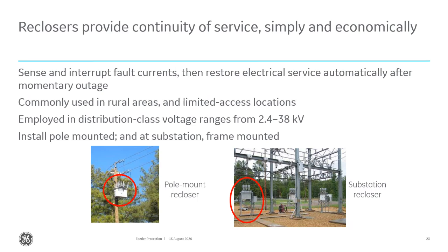Commonly, auto reclosers are pole mounted, but there are cases where they can be pad mounted for underground applications. They are usually deployed at distribution class voltage levels. At transmission level, we don't use auto reclosers. We use the breakers as auto reclosers because the short circuit current is much higher, because of all the sources in the transmission system. Reclosers are not going to cut it to interrupt those short circuit currents and for the continuous rating. So they're relegated mostly to the distribution world.